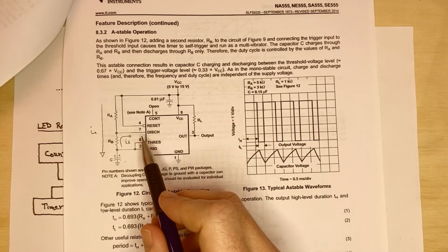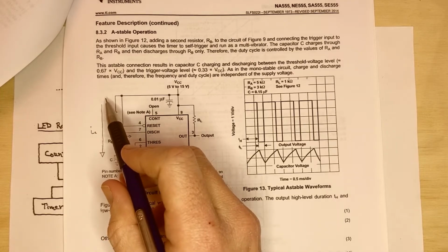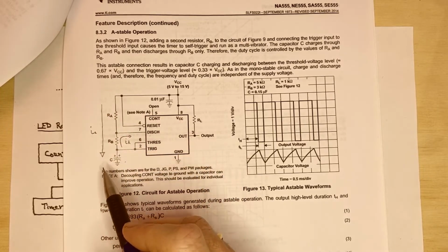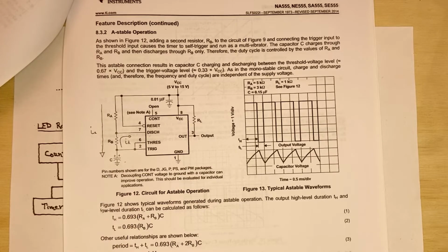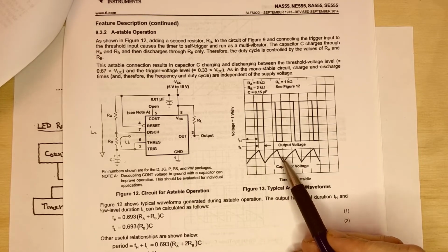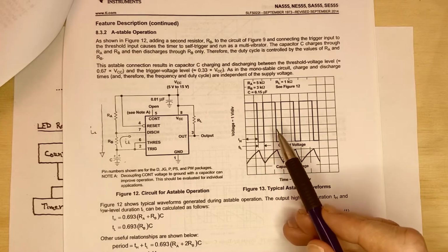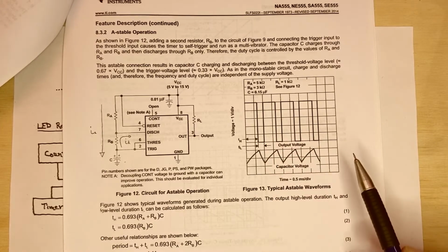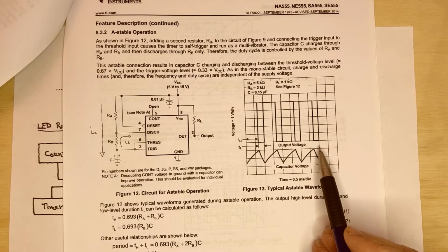And so once it's an open circuit, it's going to recharge from our 5 volts back down through resistors A and B. And it's going to basically alternate between these two states. You see the capacitor charge, discharge, and correspondingly our output voltage is going to go from low to high and low to high. And that's how we get our square wave at the output. And this was going to be our clock signal.